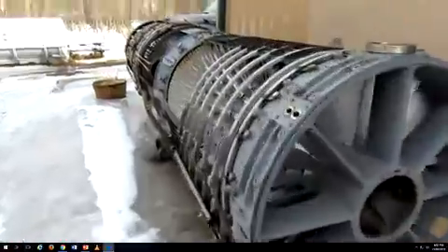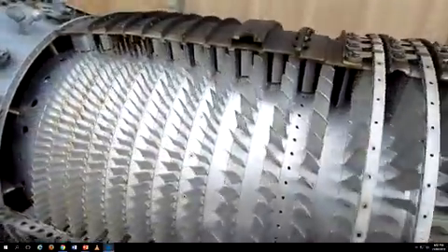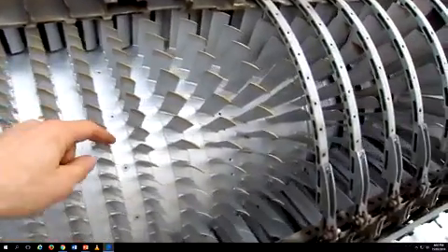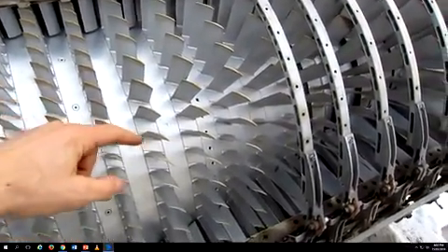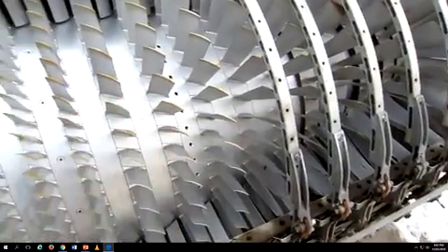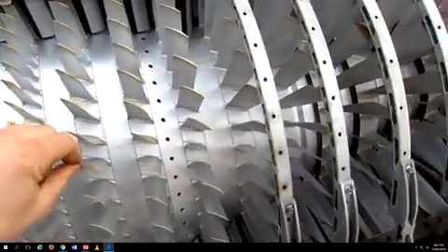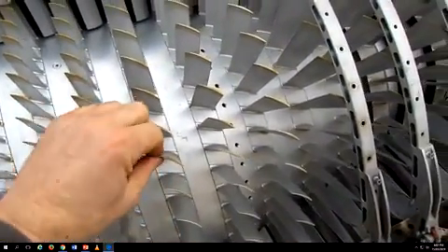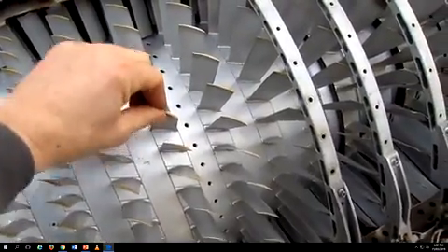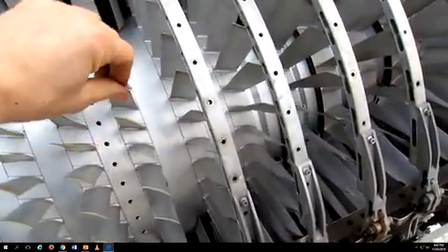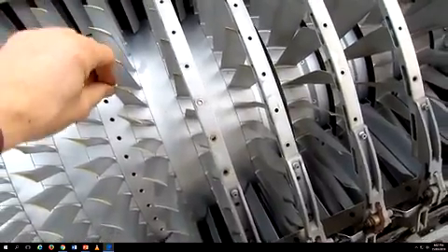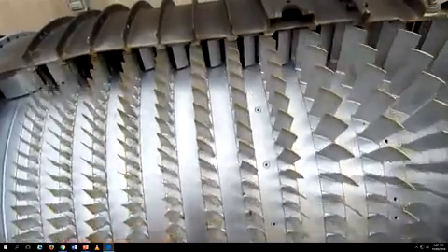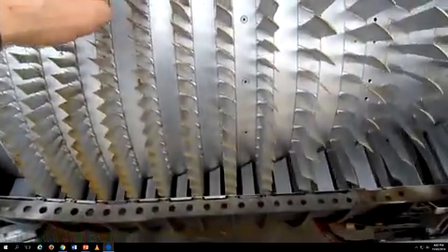Here we are outside with our cutaway. This is the exact same thing we were just looking at. This is an LM1500 J79 rotor. And what's different about these blades is they're all rusted solid into their wheel. They're corroded and full of dirt right down there in their mounting, so that they're solid. This is a very dangerous situation if this would be a running engine, because they would probably start to ring and vibrate and crack. This is our cutaway model. And that's the sound of dirt trapped down in there.